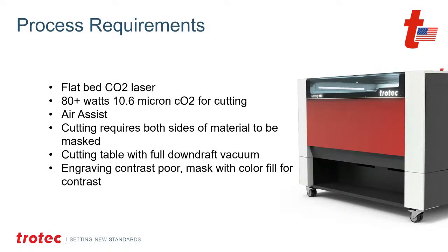So flatbed laser, 80 plus watts, 10.6 is recommended for any decent productivity. Realistically, any wattage will affect it. You can engrave it, especially if you're cutting it. I do recommend higher wattage because it is kind of a dense plastic. Air assist is a must. Cutting requires both sides of the material to be masked in order to protect it, kind of like I showed you with the polycarbonate.